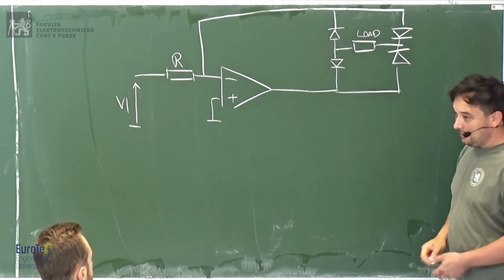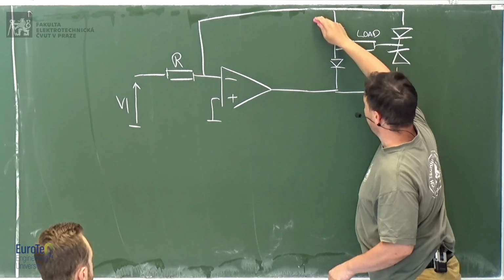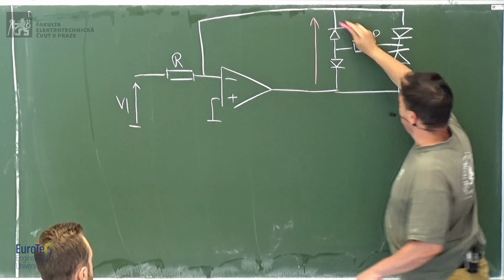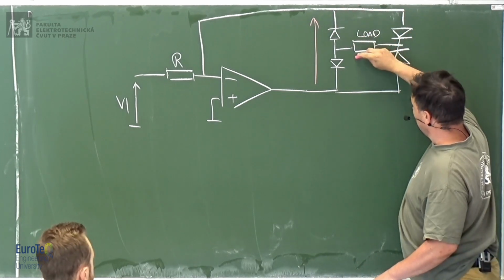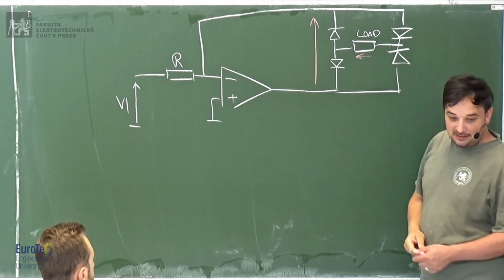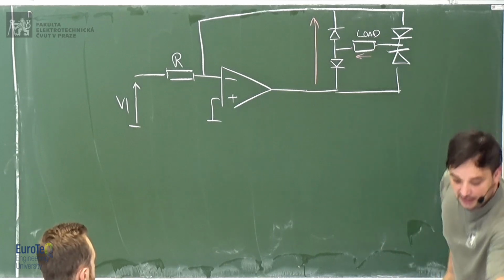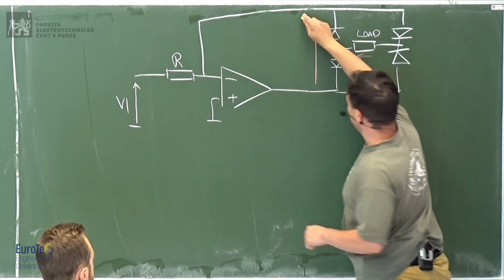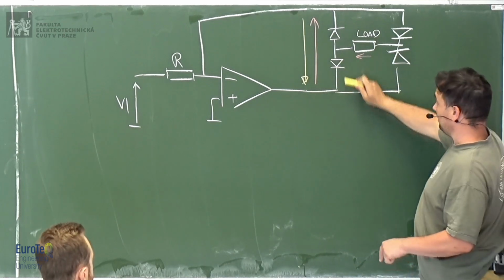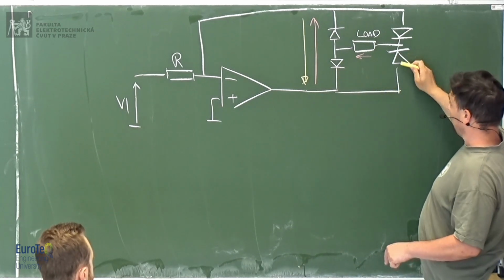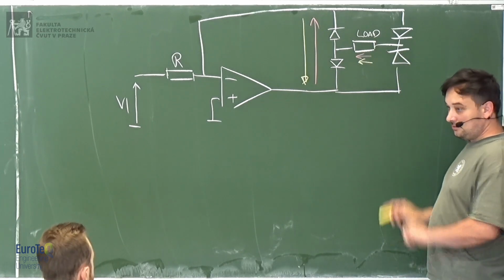Again, if you follow the rule, when the voltage arrives here in this direction, it cannot enter here, but it goes in this direction. So the current will be like that because it's going through this way. And when the voltage is negative, it comes here, cannot go against this diode, so it goes through this diode, and again, still going the same direction.